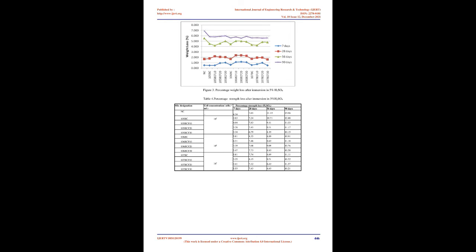3.4 Water. Locally available potable water conforming to IS 456 is used. 3.5 Fly ash. Fly ash of class F with 2.32 specific gravity is used. 3.6 Microorganisms. Sporosarcina pasteurii, a soil bacterium which is cultured and grown at the Laboratory of Biotechnology Department, CBIT, is used in 10^5, 10^6 and 10^7 cells/ml concentrations. Calcium lactate is added at 1% of mass of cement. 3.7 Grade designation, M40 grade concrete.